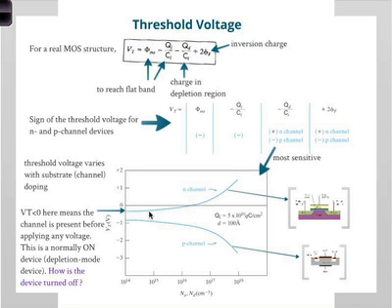So if I apply 0 volts, I had a situation like this, where I don't have a bias. I have a channel, but I am in the linear portion of the channel, so I don't get any amplification. Okay? And I can never turn it off. So I cannot switch it off. So that's problematic, like I said before.